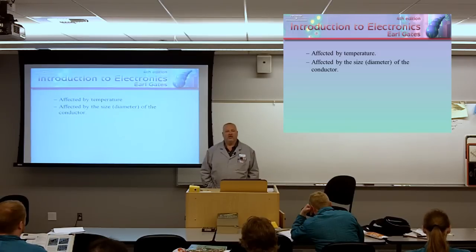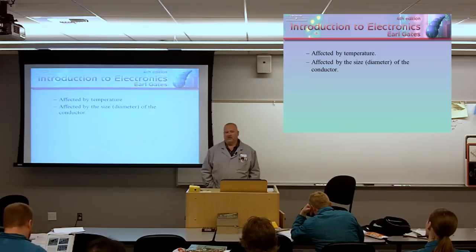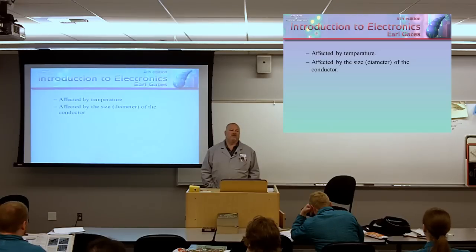In your home, the majority of circuits are 15 amp circuits. They can handle up to 15 amps. Standard electrical code dictates that you need to use at least 14 gauge wire for those circuits. For 20 amp circuits, you have some in your house, maybe in your kitchen or out in your garage, your workroom, your utility room. Electrical code dictates that you have 12 gauge wire minimum. That means that the wire is thick enough to support the flow of 20 amps of current.